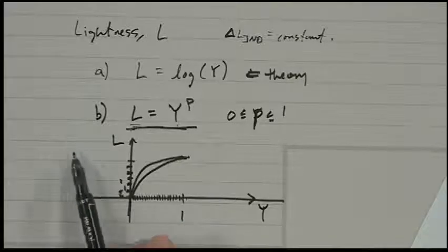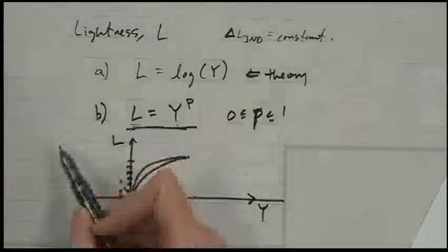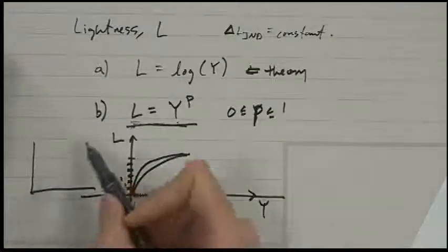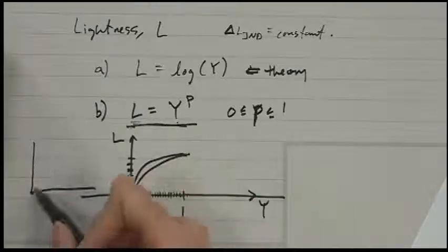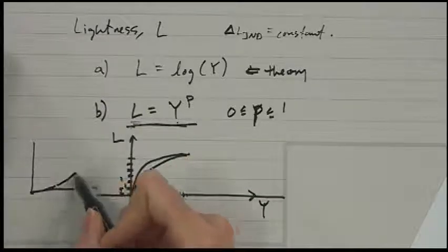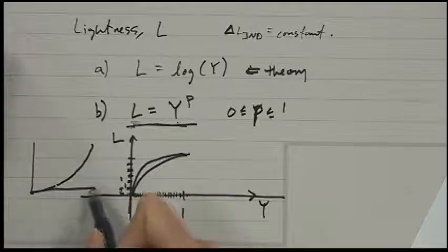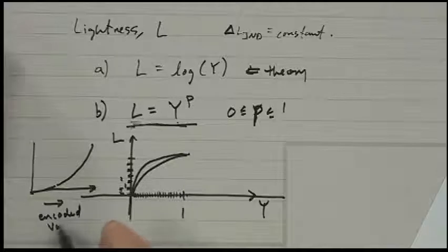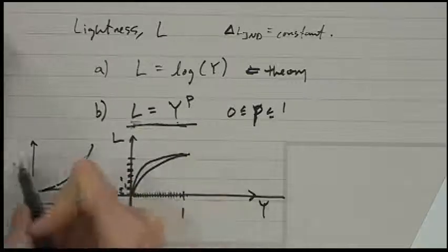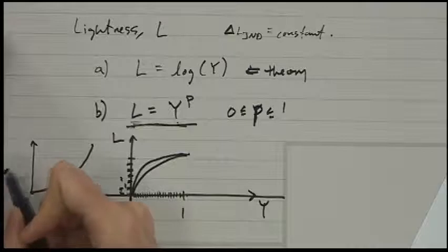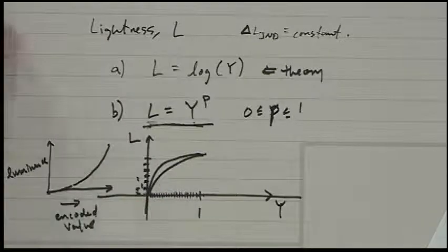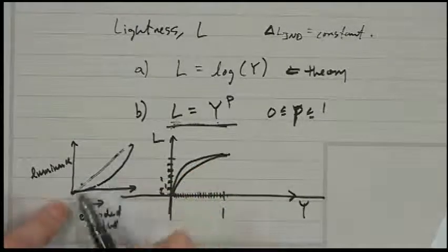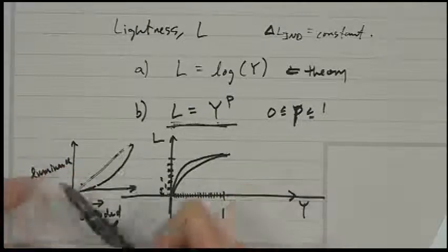And when you viewed the image that was ungamma corrected, it looked dark, because the display device has a response that goes like this, where here your encoded value is along this axis, and this is the corresponding luminance that's produced by the pixels. The monitor effectively has this response, and so it appears too dark because everything is being shifted down in terms of luminance.